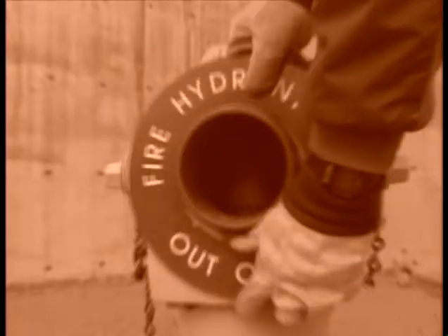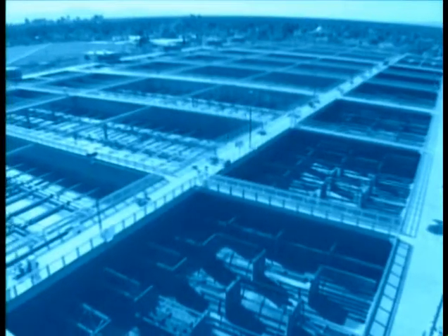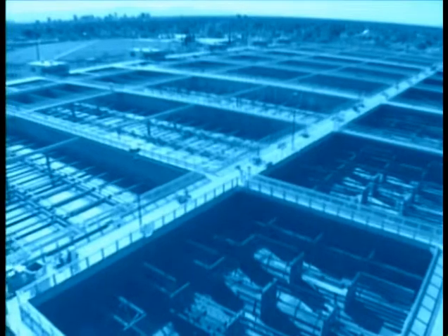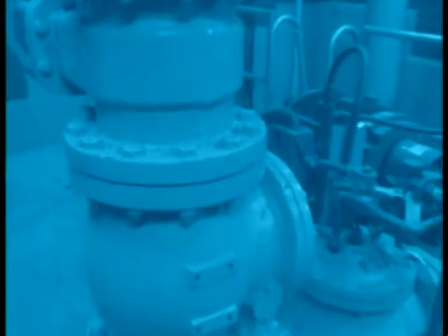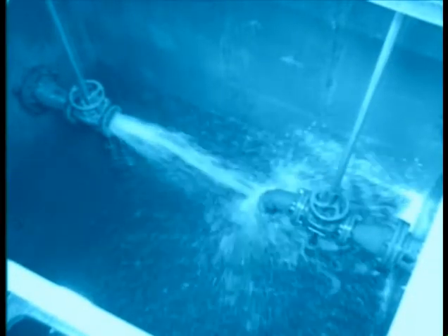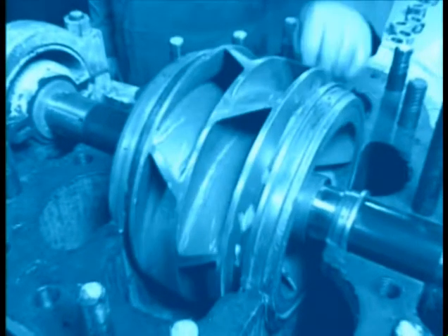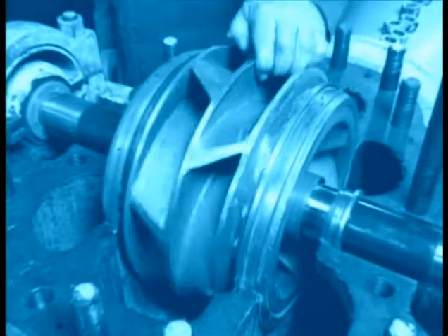The utility immediately began marking out-of-service hydrants and scheduled meetings with local fire departments to discuss the procedure. There have been numerous other incidents or near misses at water utilities, including those in water treatment plants when pumps were not properly locked and tagged out and water suddenly flowed into filter beds or storage areas under repair. And injuries have also occurred during the maintenance and repair of pumps and valves in a plant's distribution system when they have unexpectedly become energized.